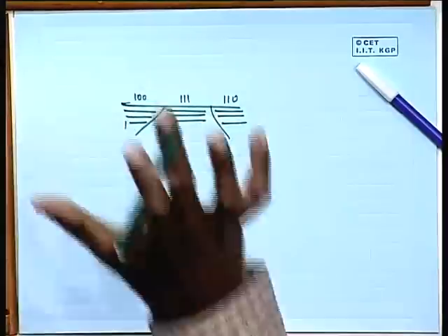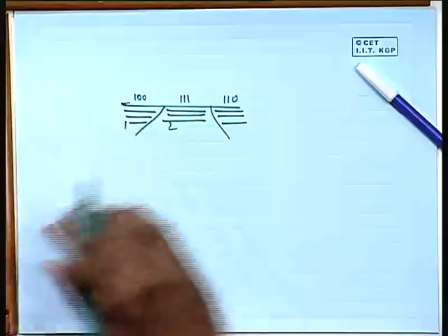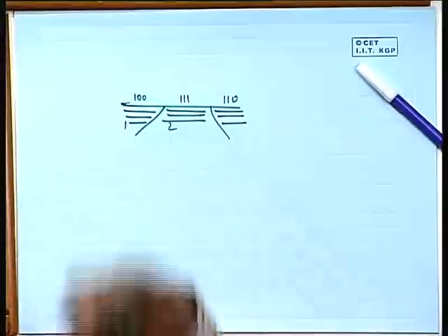If you look at 3 different grains, because you are cutting a surface, polishing it and putting an etchant on it, each grain will have a different plane which is parallel to the surface. If they are the same planes, then you do not call it a different grain. So we say each grain has an orientation difference. The same plane cannot be parallel in grain 1 and grain 2 for the top surface. Each grain should have a different plane which is parallel to the top surface.